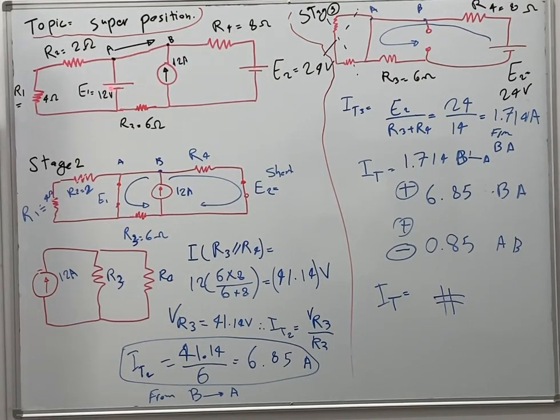Then, like we mentioned in part 1 where you mentioned some text here, we'll make E1 shorted and we'll make E2 shorted. So now we are just dealing with the current source here, which is 12 ampere. This is the redrawing for stage 2. These are the shorts. This short will cancel the effect of R1 and R2, and this one will make it easier.